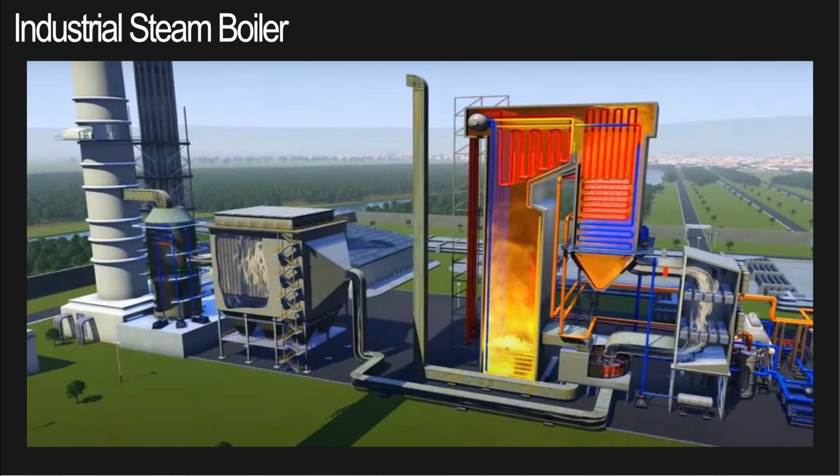Perfect. So now, moving to the cool part of thermodynamics and combustion reactions based on what we have stated so far. So going to the industrial boiler. Here we have a picture of what I would see if I cut through a package boiler. This is pretty much the furnace of the boiler. You have here the combustion air coming through this line. This is the combustion air, okay? The natural gas would be coming through these lines inside, and it's going to be meeting the combustion air in this flame, in that burner, and they're going to ignite.